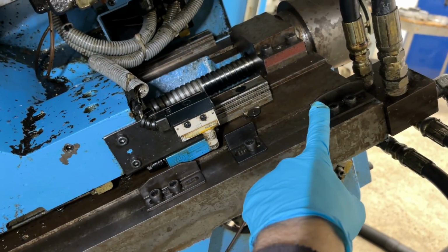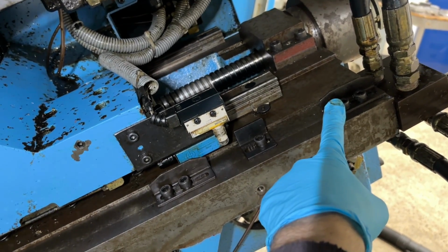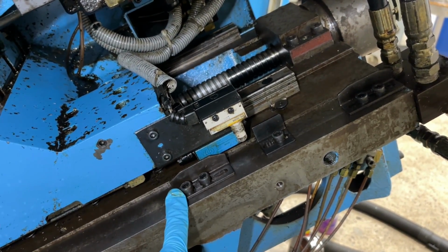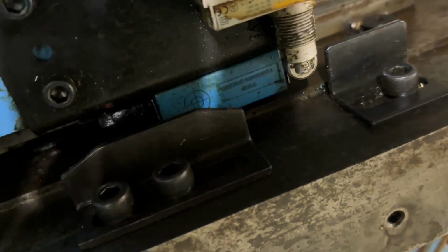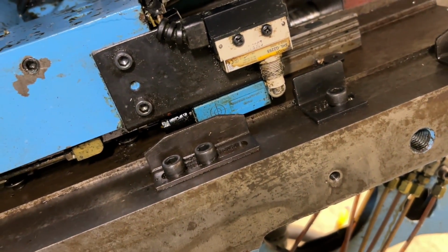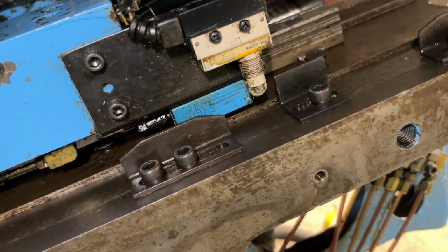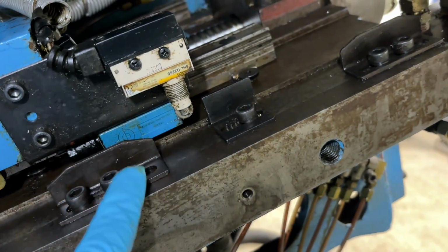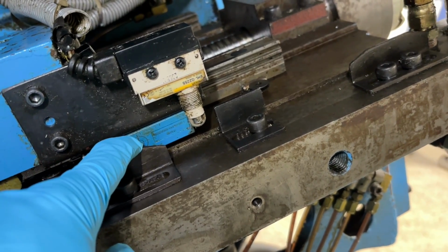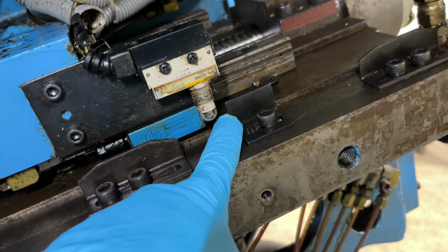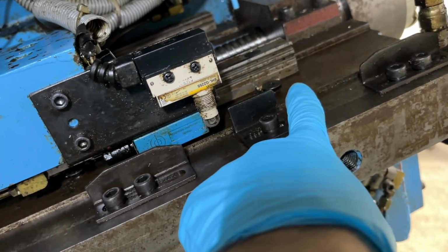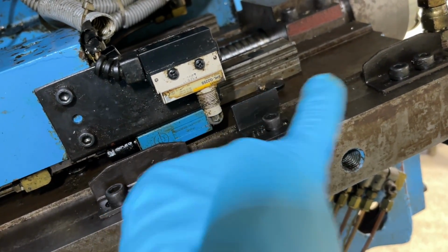So this is the X positive limit switch dog. This is the X negative one. Now this is the proximity sensor dog. And this blue guy in here with the target on it, that's the proximity sensor. So this is the piece I've been having problems with. I haven't been having any issues with this. The problem is the proximity sensor would stop when the target gets to about this point when it needed to be up here. So it needed to go past this thing.